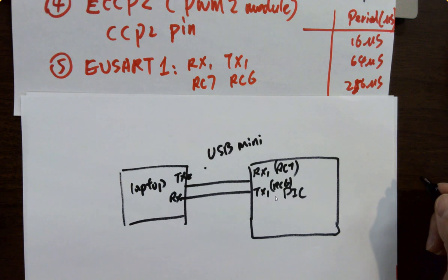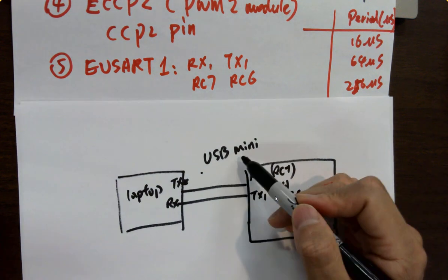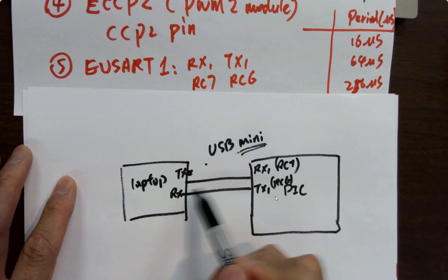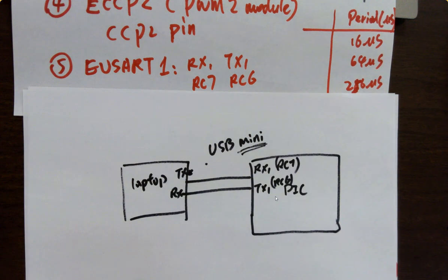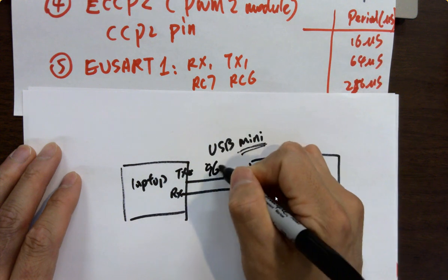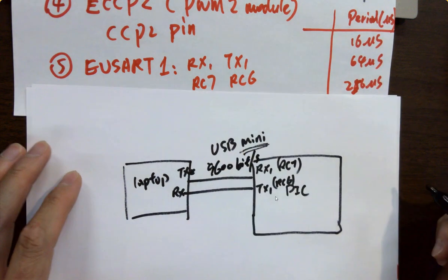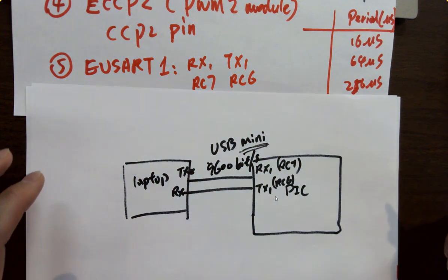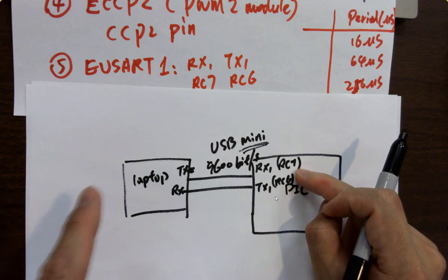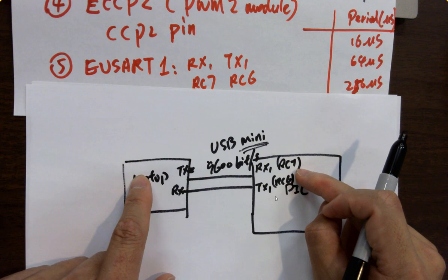If you are trying to debug, and you see, hey, I'm not seeing the COM port on my computer, which one is possibly having a problem? It's only possibly something to do with the mini cable. If you replace the micro cable, it's not changing anything, because the UART connections go through the mini cable, the bigger one. What's the bit rate? You get to choose the rate. You can change it through PuTTY. So if you want to change it here in UART1, you have to change it through PuTTY accordingly, so they match.